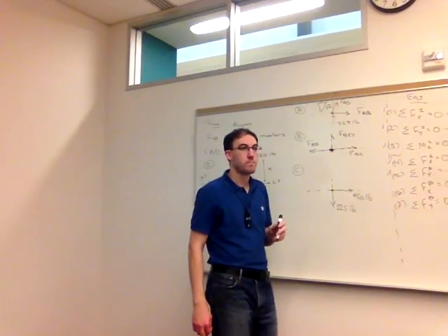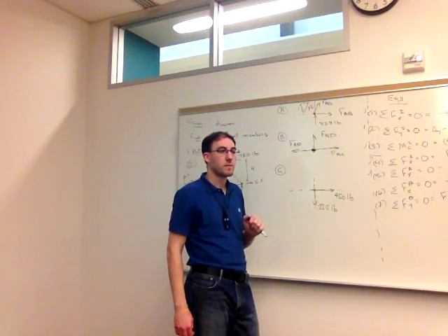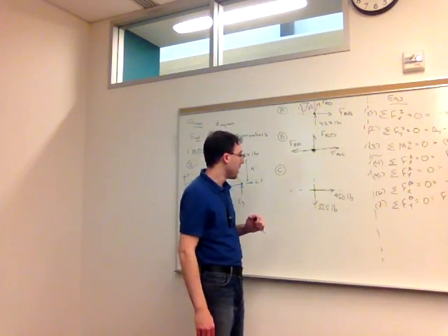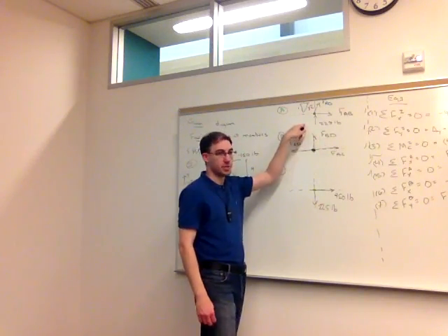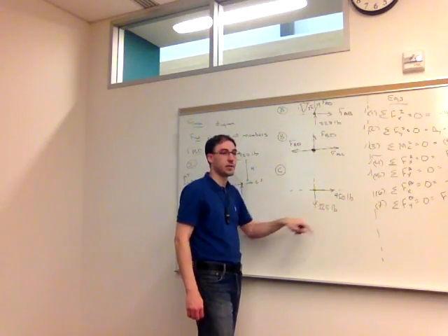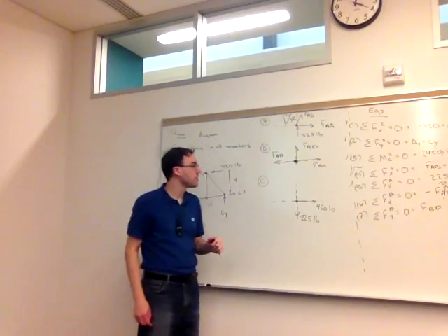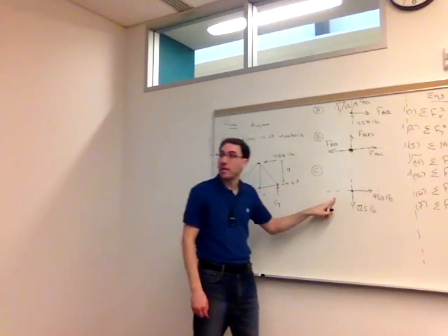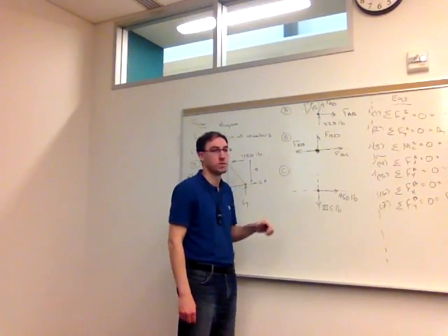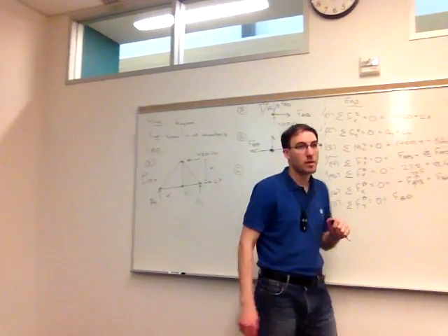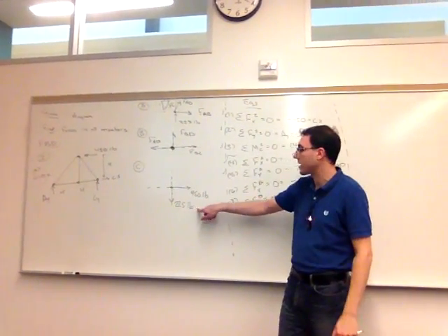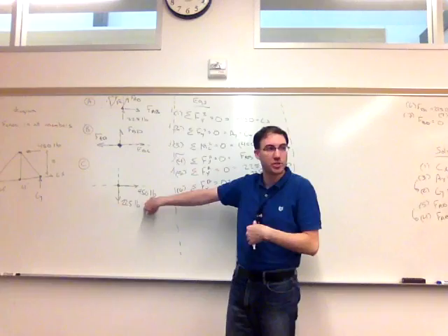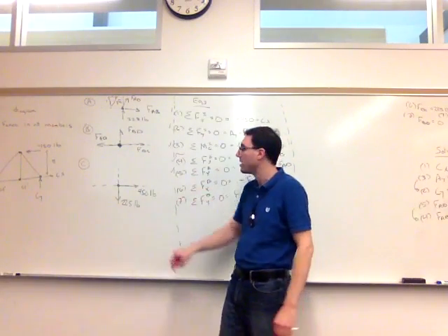I thought for the free body diagrams, you wanted us to leave it in variable forces. For the internal forces, you should. For the external ones, it's okay to use the actual numbers. Yep. So for the FBC and FCD, those I'll leave as variables. All right. So those are the 2 external forces. Again, I chose to, at this point, draw the 225 in the correct direction.